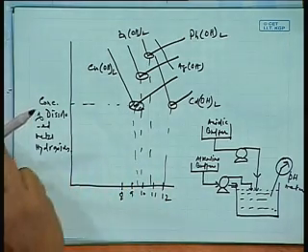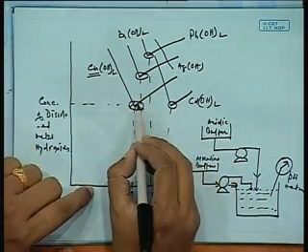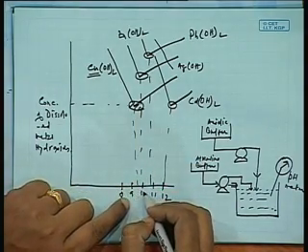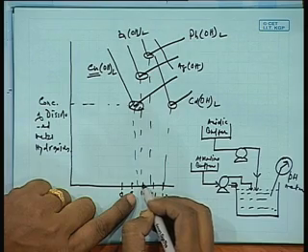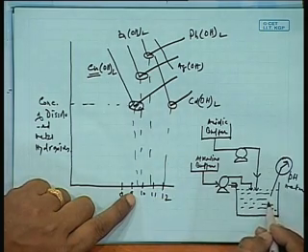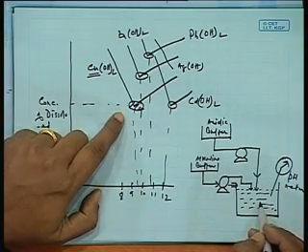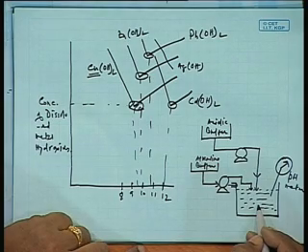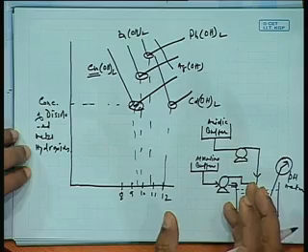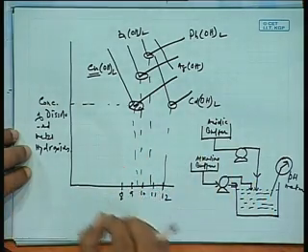If you are targeting copper, you would run a stream where you try to maintain the pH at about 8.5, so that most of the copper hydroxide precipitates. If copper hydroxide is precipitating, the concentration of metal in the solution is going down.